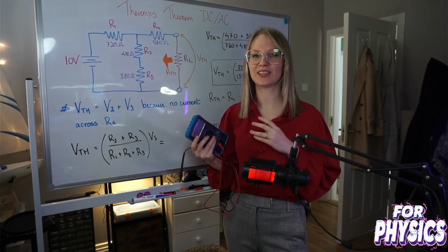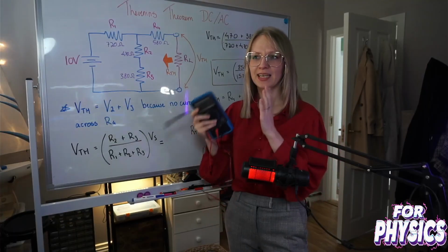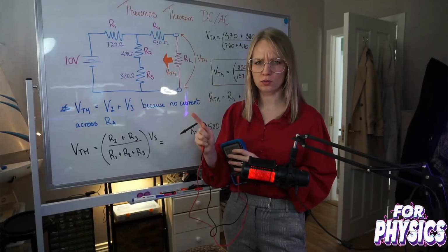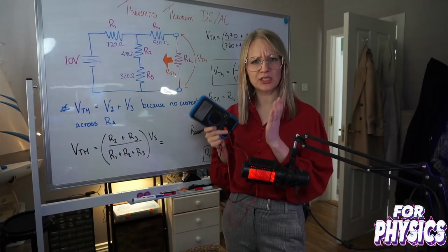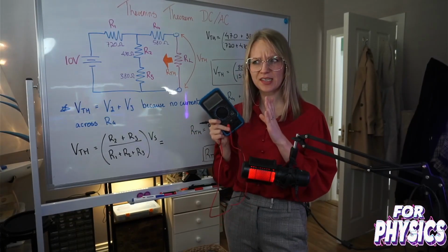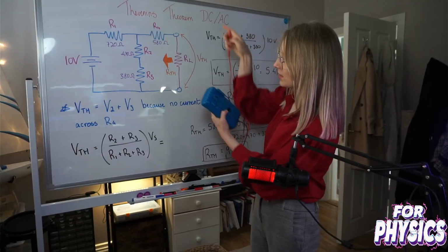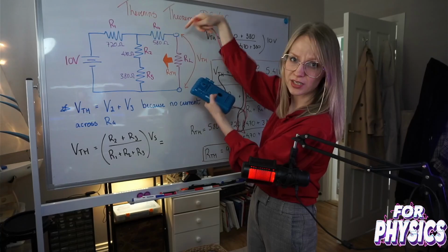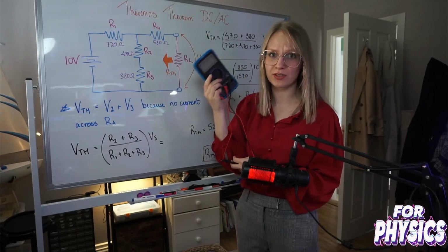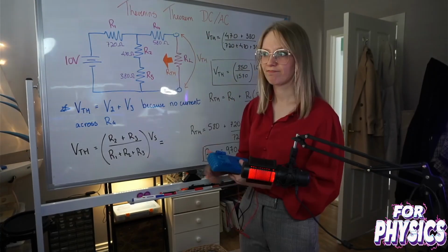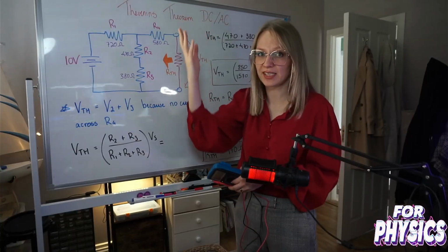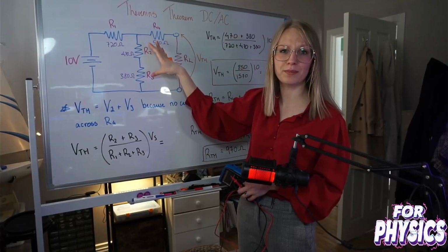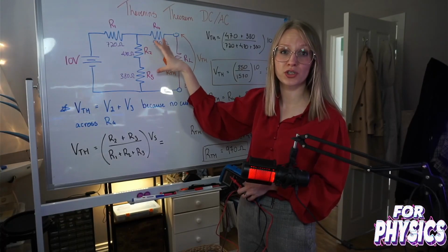The way I like to teach things is applied and practically. Literally grab a voltmeter and measure this circuit, but also think about what a voltmeter is. It's basically just a giant resistor. If you put it across, just have a 580 ohm resistor in series with another giant resistor, let's say infinite size. Infinity plus another number is just infinity. So there is no current being passed through here. Hence, we're only measuring the voltage across these 2 resistors, R2 and R3.